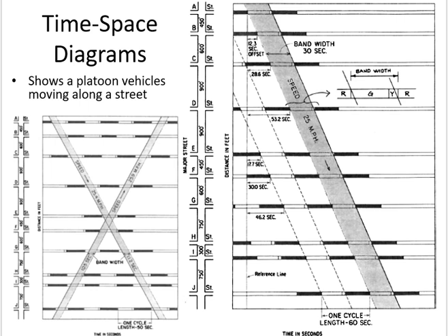Okay, clear? So I was making the point that I know the first green starts after 12.3 seconds. Then whatever green time I have designed, I will give this much. Then whatever yellow time I've designed, I'll give this much. Then the red, according to my calculations and so on. So the rest of these things will continue. Now coming back to coordination.